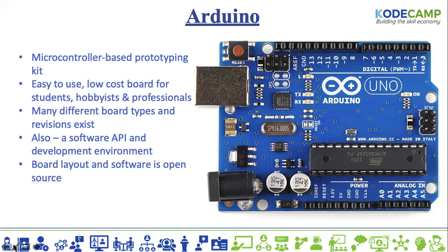From 0 to 13 makes it 14 GPIO pins. Now, these RX and TX can also be used for input and output, but most times they're used for serial communications. If you're sending data from the Arduino to another microcontroller or microprocessor, you can use that TX and RX. But aside from that, it's also a GPIO. You can send data out of it, and you can receive data.